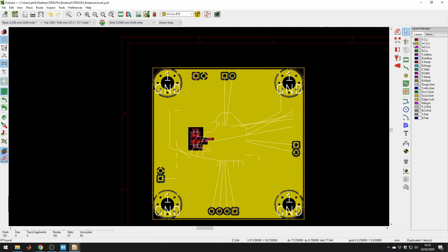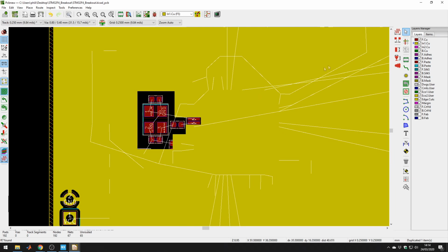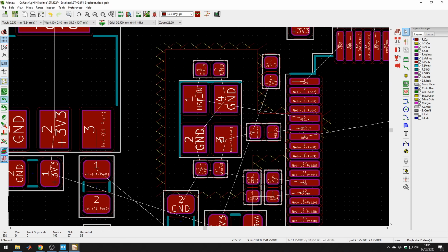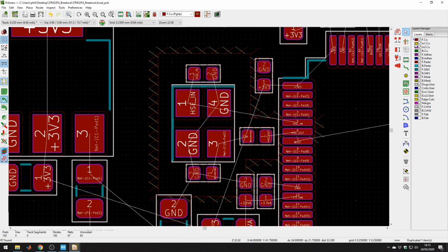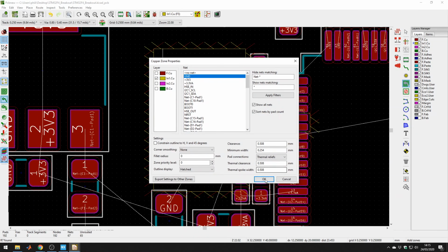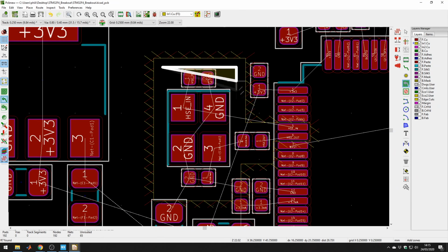And all of them have the same shape, so they all have this cutout around the crystal oscillator, and this is what we want. Because now we are going to put in the inner layer, so the second layer, a little ground fill in here. And that's going to be the local crystal ground. Let's do that. So starting somewhere here, ground, and let's just trace it out.